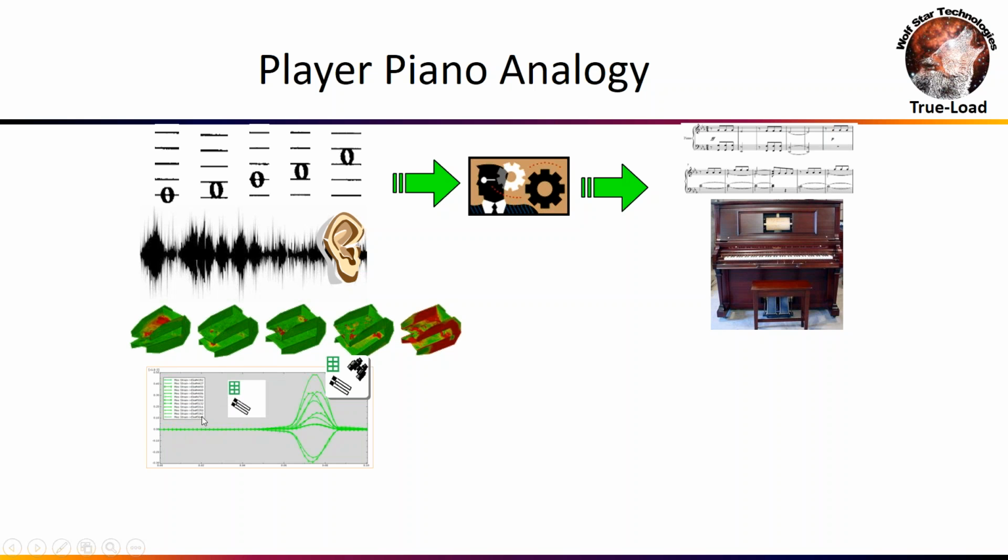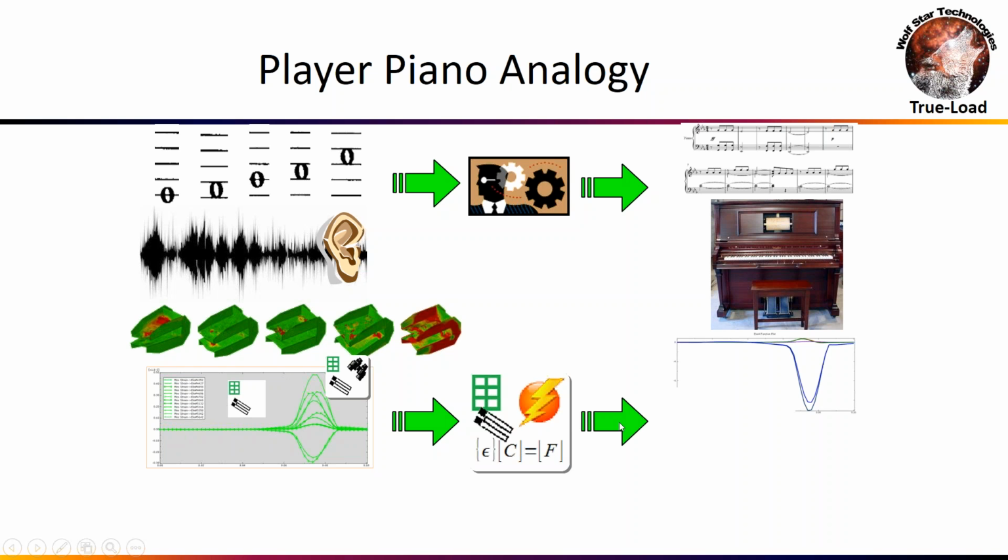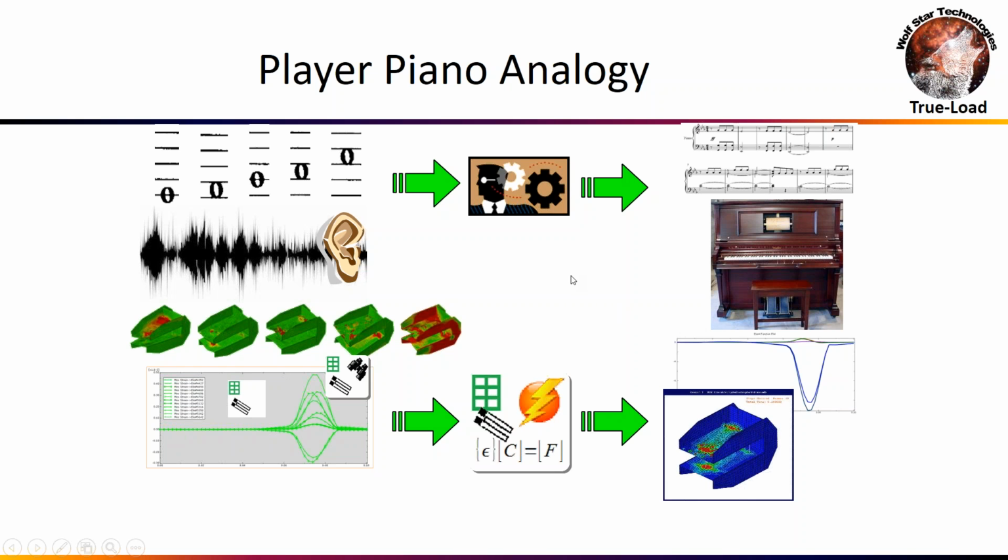We'll place the strain gauges on the physical parts and measure the time histories of strains on the physical parts. And we'll take these measured time histories of strains and multiply them by the correlation matrix that we stored to disk to generate loading functions. We'll get this nice time history of loads that shows how much each one of these unit load cases responds in the full field of the part. Then we can play that back together to reproduce the full field effects of what was going on in the actual part.